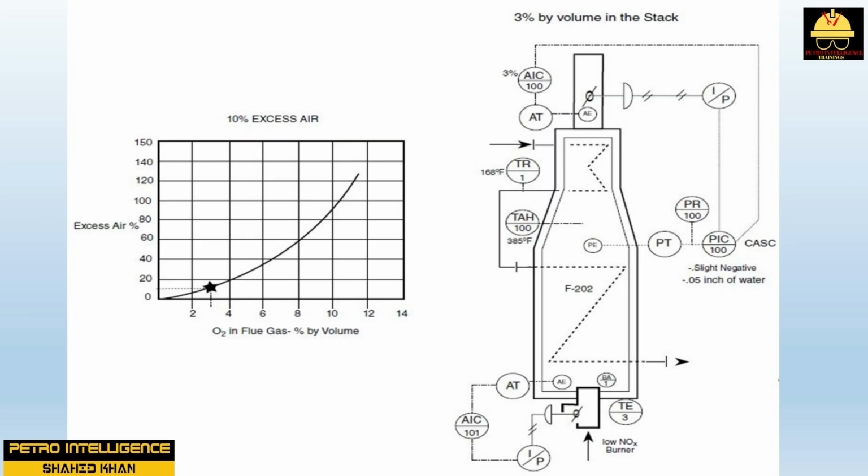By decreasing the excess air flowing through the process heater, a technician can save money and more easily achieve product specification. Some process heaters utilize advanced control instrumentation that maintains a preset ratio of air to fuel. For example, a ratio of 11 means that for each weight unit, kilograms or pounds, of fuel, there are 11 similar units of oxygen being supplied. Higher ratios indicate that there is more excess air. A lower ratio translates to less excess air.